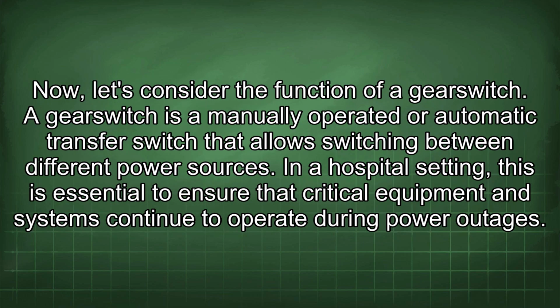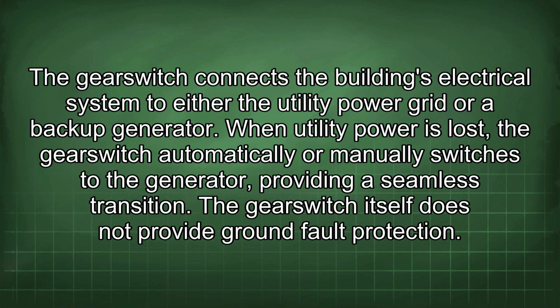Now let's consider the function of a transfer switch. A transfer switch is a manually operated or automatic switch that allows switching between different power sources. In a hospital setting, this is essential to ensure that critical equipment and systems continue to operate during power outages. The switch connects the building's electrical system to either the utility power grid or a backup generator. When utility power is lost, the switch automatically or manually switches to the generator, providing a seamless transition.